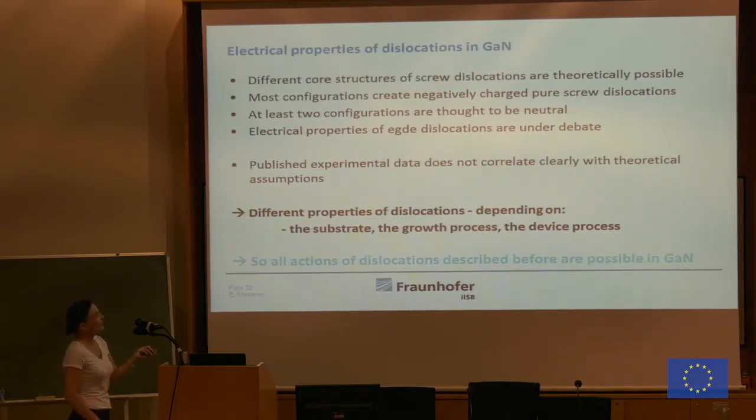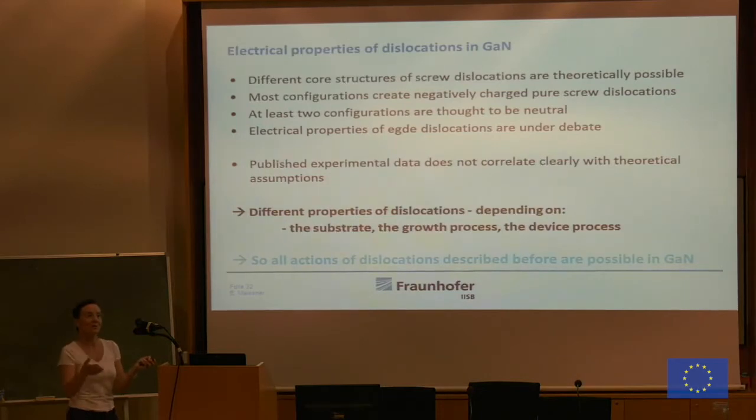And it also depends on the generation of the material. So what history does the material have? What was the substrate it was grown on? What is the process it was grown with? What is the device process later on? How many temperature steps, at what temperatures does it experience, and so on.